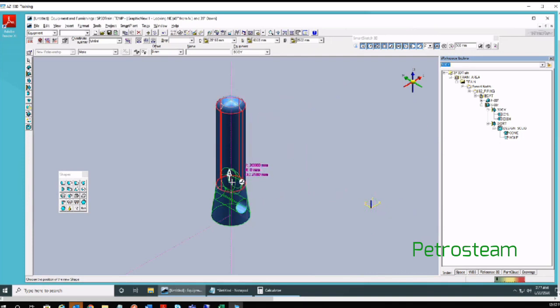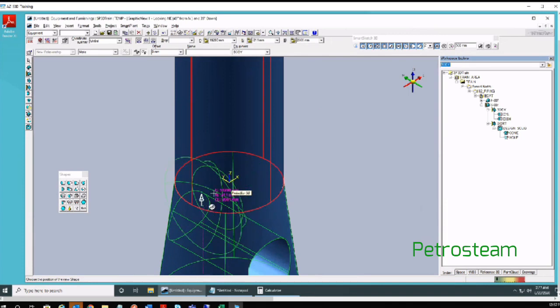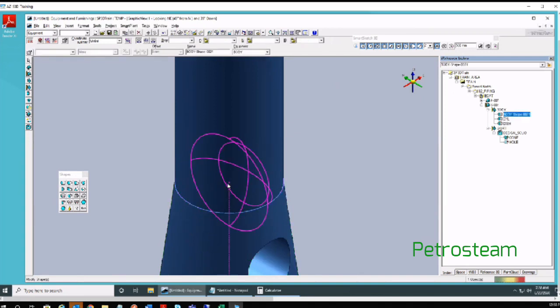After that, you can place it wherever you want. You can see at the top, it is showing easting 20, northing 0, elevation 2 meters. That is where I want it. If you are sure, you left click to accept the location. After that, how will you come to know in what direction it is?